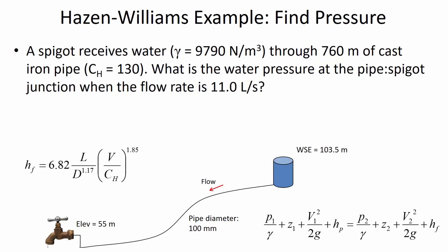The energy at this tank, at the origin, is potential energy, and it's causing pressurization downstream, and it's also giving up energy to losses. What the Hazen-Williams equation, which is shown here, helps us to calculate is the losses side of things in an easy, direct way.